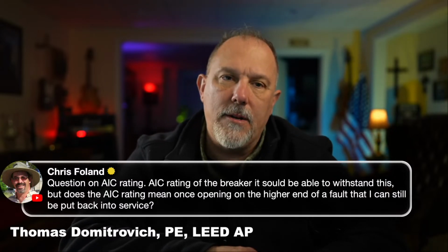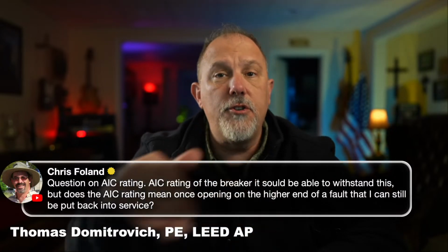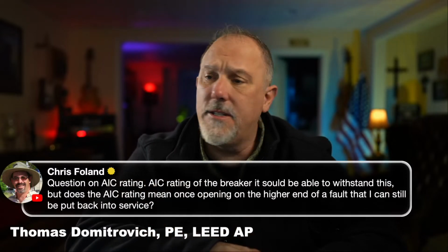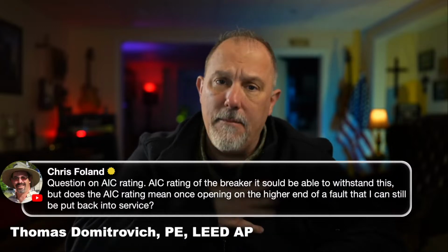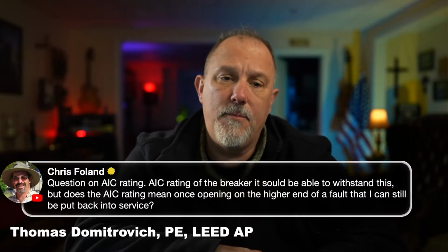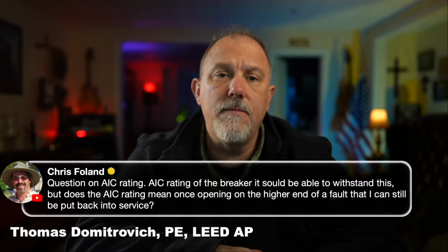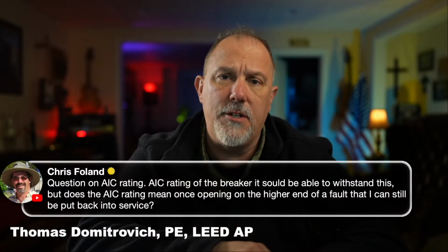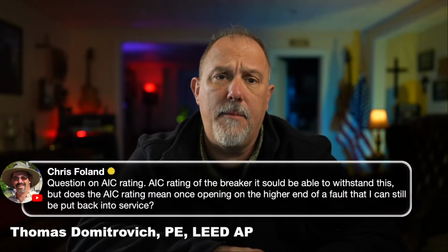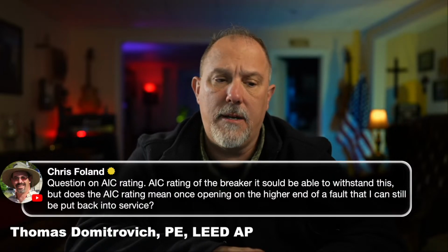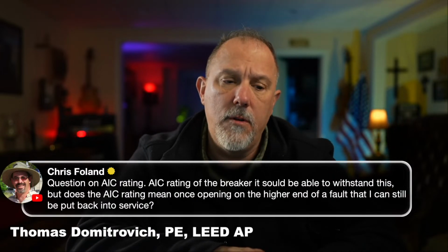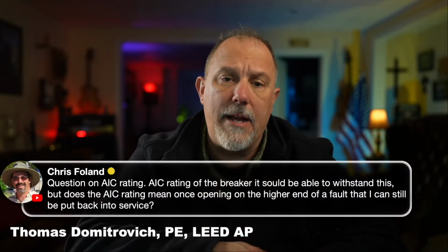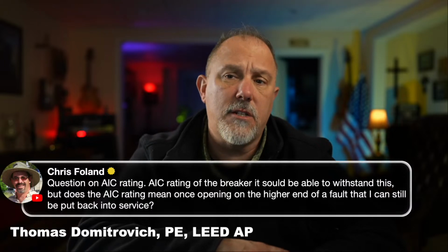I take a hit on a breaker, especially once you do your troubleshooting and you know it was a short circuit, you can estimate what the value was. Chris, my suggestion, plop another one in there, take that one out, take a look at it, run through the NEMA AB4, see what you can do, and then maybe use it as a backup for later. I would just feel comfortable knowing, because a lot of our guys and gals out there rely on that for arc flash calculations and all this other good stuff.